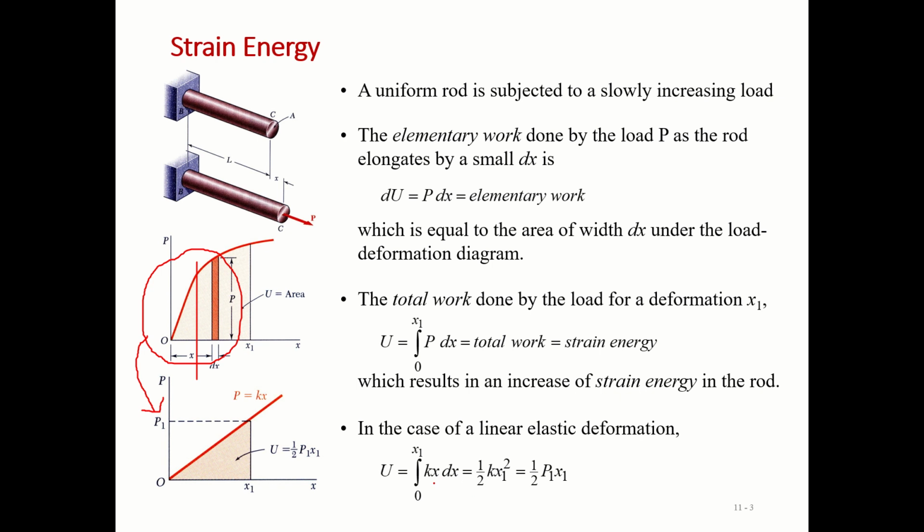So integrating for the whole length of the elastic portion, the linear elastic deformation will be equal to 1 over 2 P1 x1, just by substituting for the K, which is the load divided by deformation. So this is the elastic strain energy or elastic deformation.